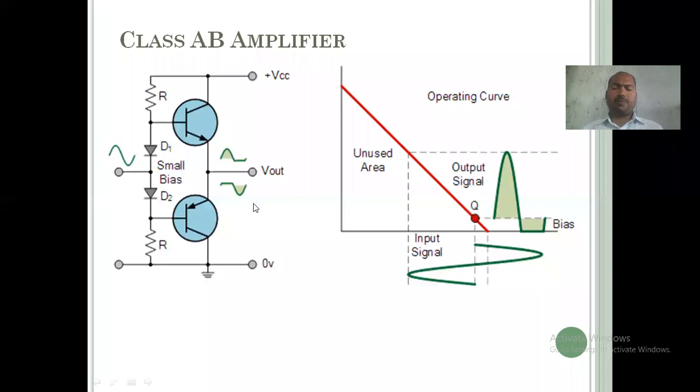type of amplifier. Okay, so see, this is the diagram of the class AB type of amplifier. We know that class AB type of amplifier has a conduction period of greater than 180, greater than 180 and less than 360 degree. So it indicates that up to this 180, and greater than this, greater than 180 and less than 360 degree is the period of this working. So whatever spike or crossover distortion comes, that should be reduced when we use the class AB type of amplifier.